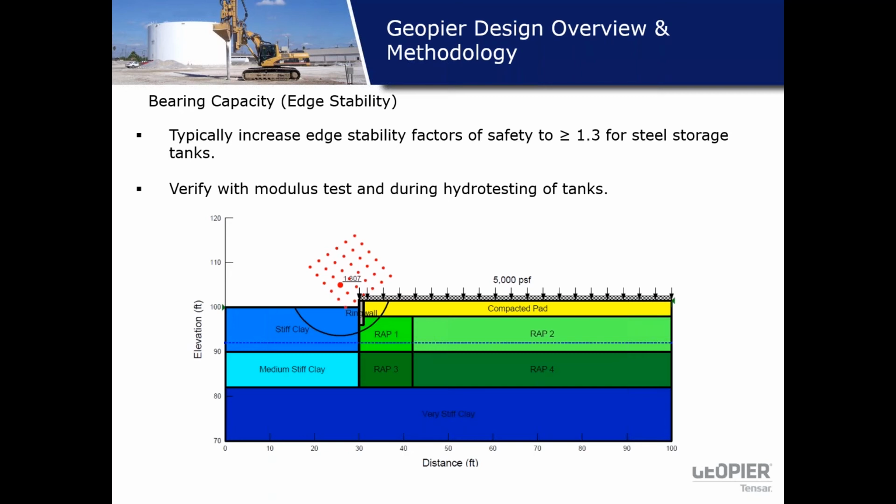And the difference is, where you have ring wall foundation or edge stability is concerned, sometimes you need piers to be installed in close spacing, and as you go inside, or the interior of the tank, pier spacing can be widened. This is simply economics, provided your differential settlement criteria works out well.